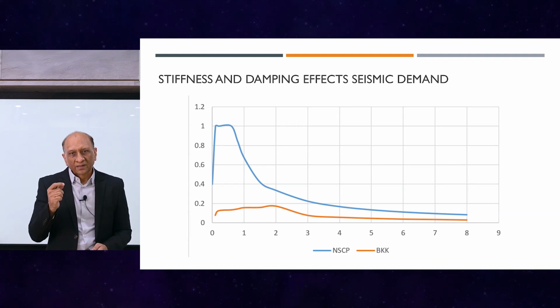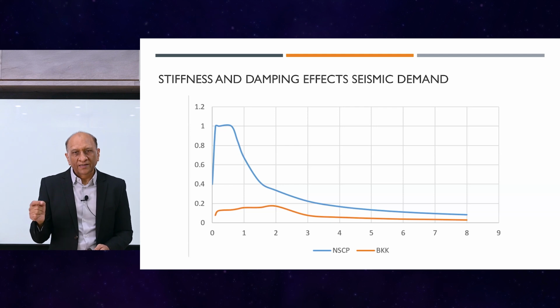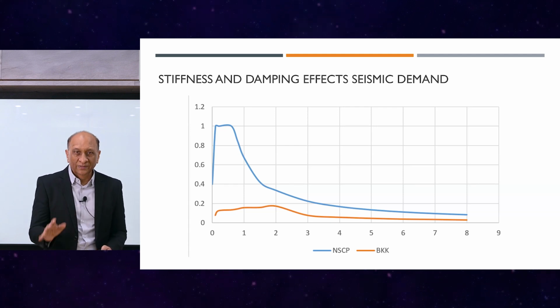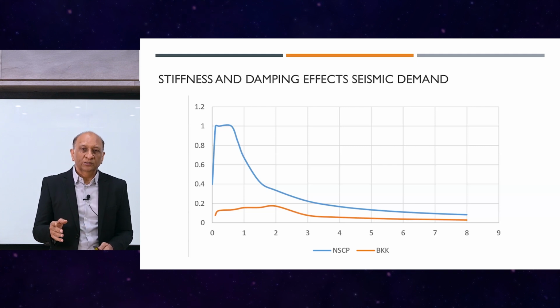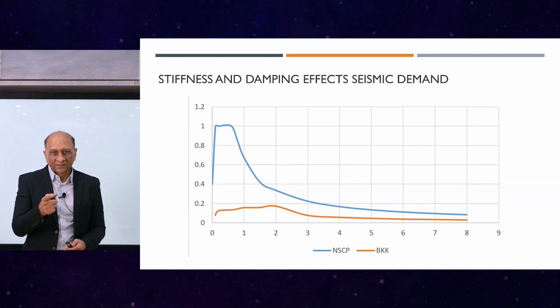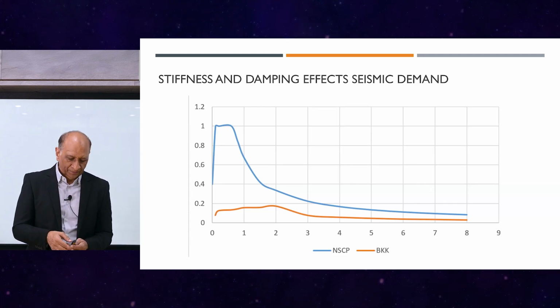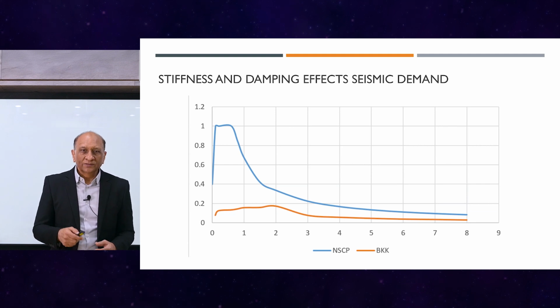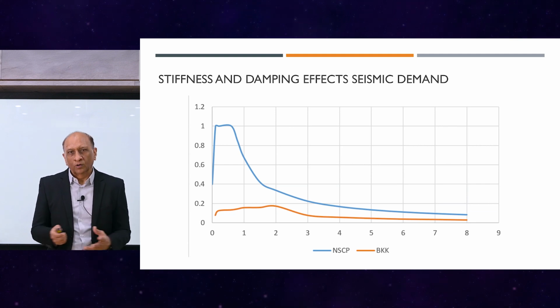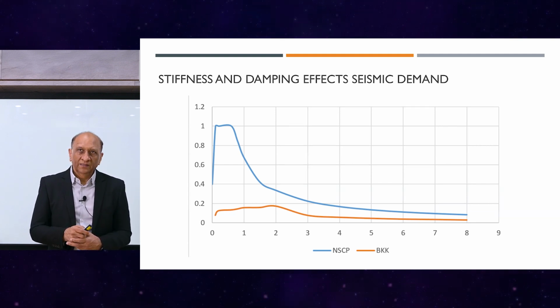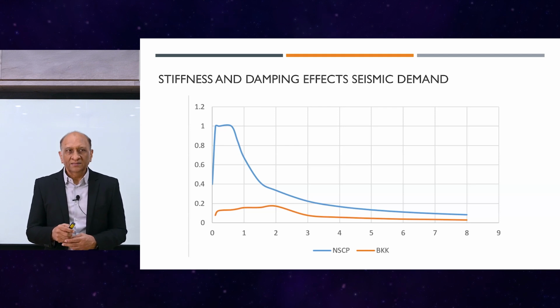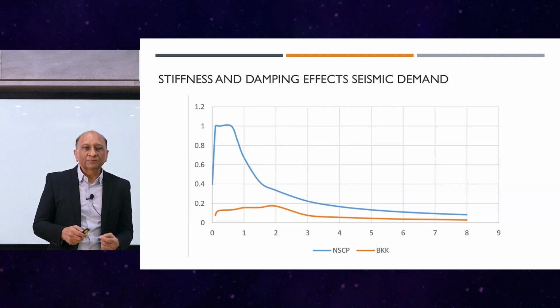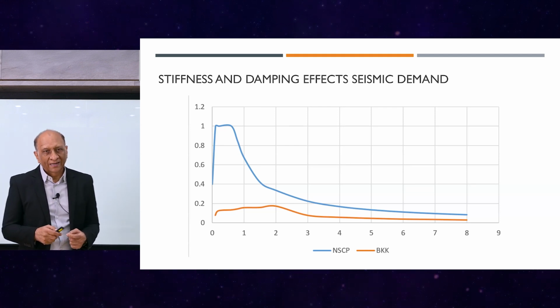So both tend to reduce the seismic demand, tend to, I said not always, tend to. Typical reduction can be between 10 to 60%, and in some cases in Bangkok, it could actually increase slightly. So that's roughly the overall summary of the stiffness reduction and damping change. Let's come down now to R and omega and Cd.